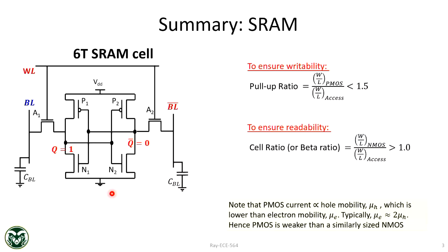the P2, N2. Right? So which one will be Q? Will this side be Q or this side be Q, looking at this diagram? So look at P1, N1. Output of P1, N1 is Q. That means this is Q. This is Q1. This is the output of an inverter. This is the input of an inverter, right? This is Q1. Make sense? Okay. So that's the storage element.